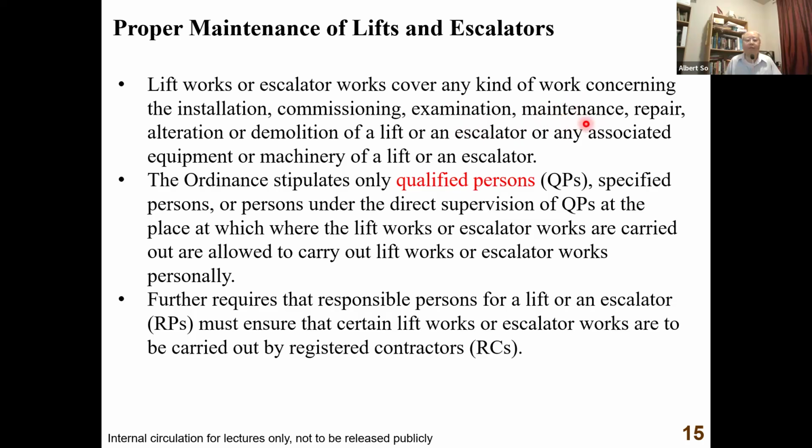Then maintenance is on a monthly basis. Also, the law requires that every lift or escalator be maintained with a period not longer than 30 days. In order to comply with this law, in industry practice the registered contractor will maintain the lift or escalator every 2 weeks. That's the industry standard, not the law. The law asks for 30 days, not a month, but 30 days.